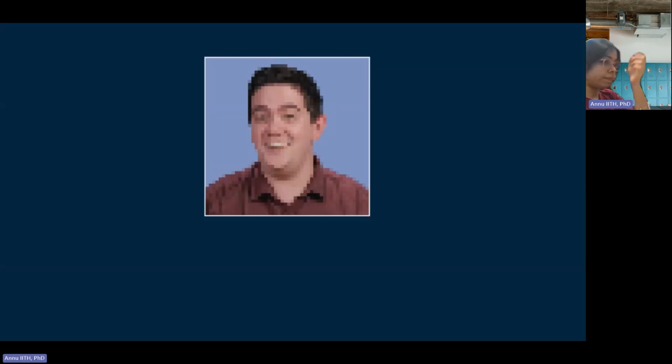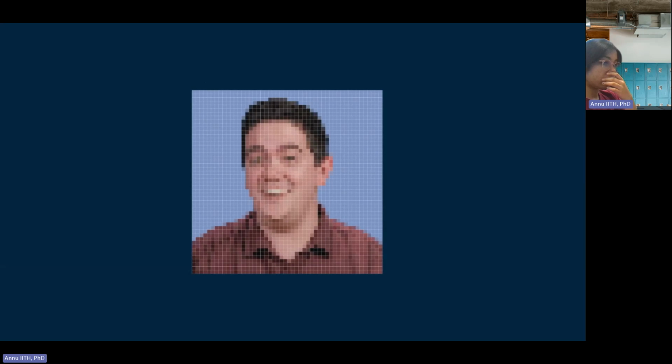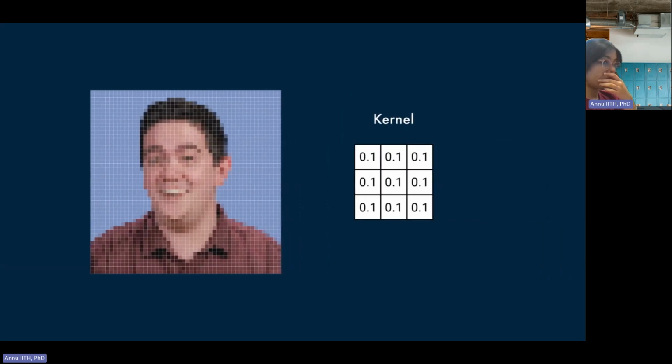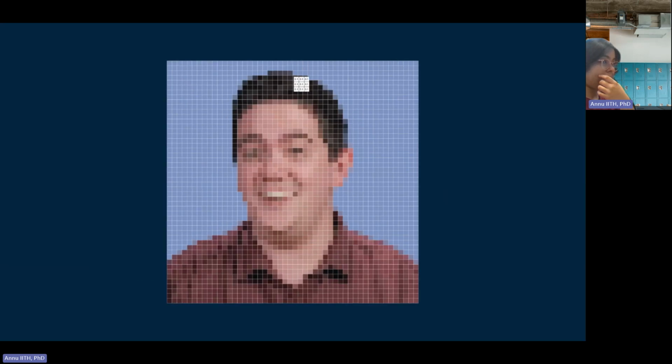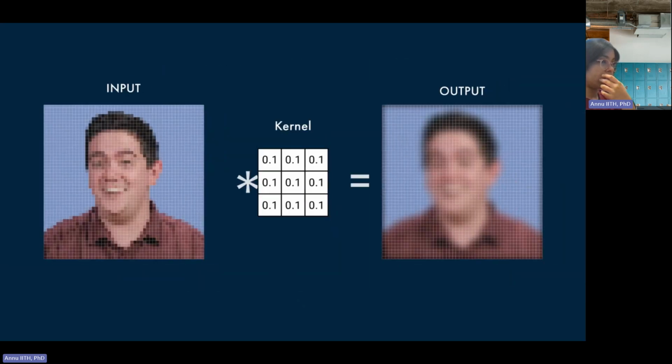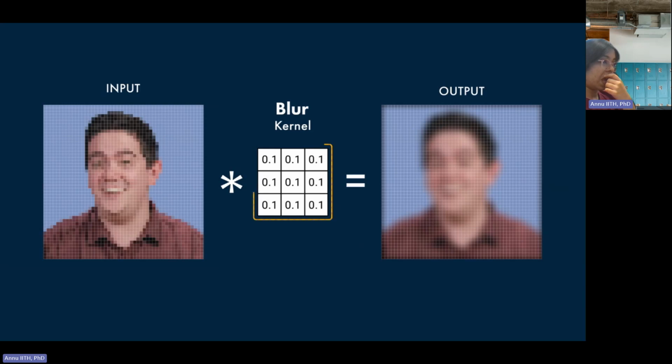To apply this to an image of yours truly, we take a kernel, a 2D filter with specific size and values in it, and pass it over the image, multiplying and summing pixel by pixel to create a product which is a modified version of the original image. I'm sure we've all seen a blurred image before, and this is precisely what it is, using a kernel with values like these to create a moving average of an image, filtering out the high frequency details and producing a blur effect.